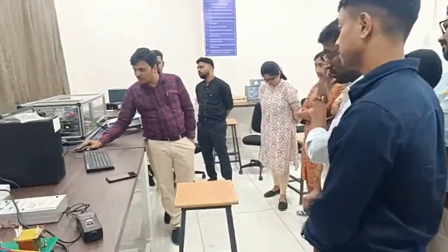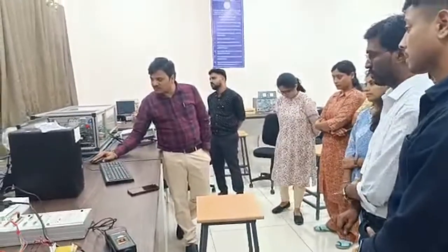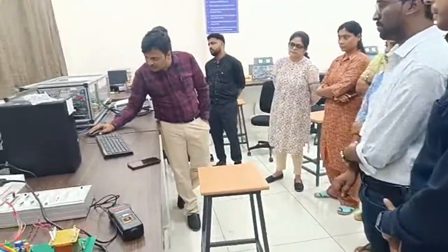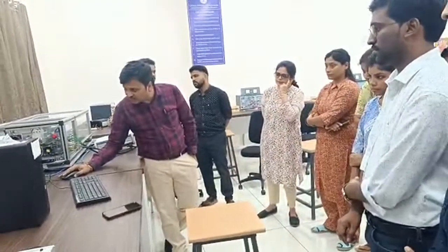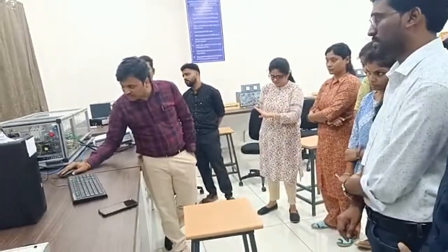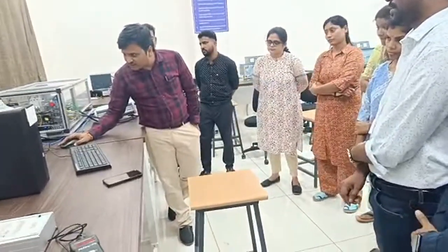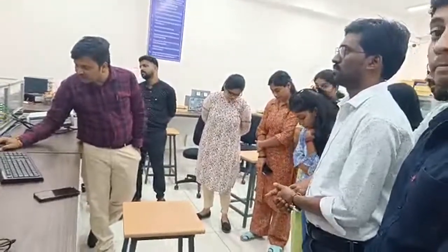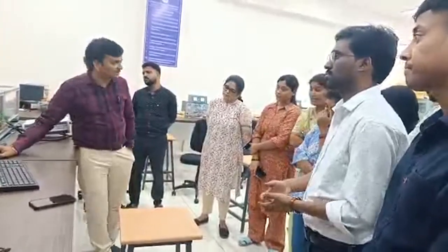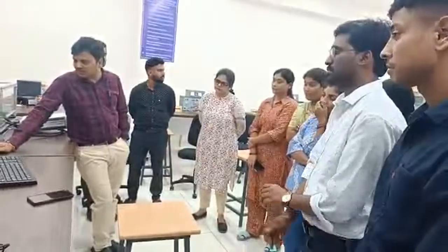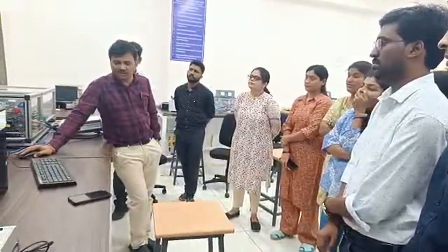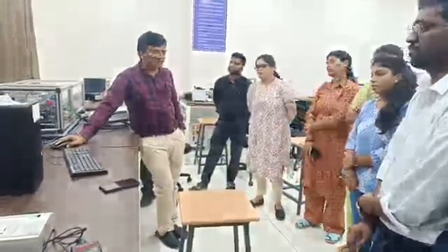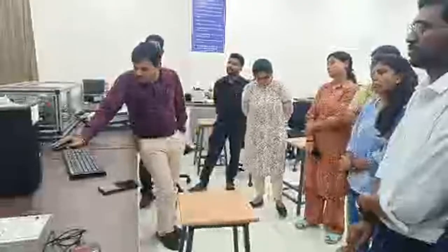Experiment 1, the ex1.sdf file, is brought here. Now I have to access these variables. You can see the variable environment at the bottom. What is there in this SDF? You can see timer task 1, model root, data type, pulse generator. All the names we have given, pulse generator, data convert, all will come here. All are variables only. The pulse generator is my variable that I want to change. I will select that.